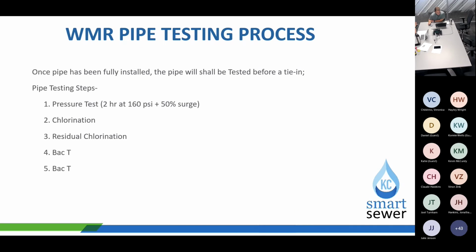You'll be needing to do a calculation for surge, the 50% surge. Usually that adds about 10 to 15 PSI to that test. So on a 6-inch main, 8-inch main, it could be 175, could be 180. If a contractor tells you that the line, oh my goodness, it's going to blow apart, that's something where they try to pull the wool over your eyes.